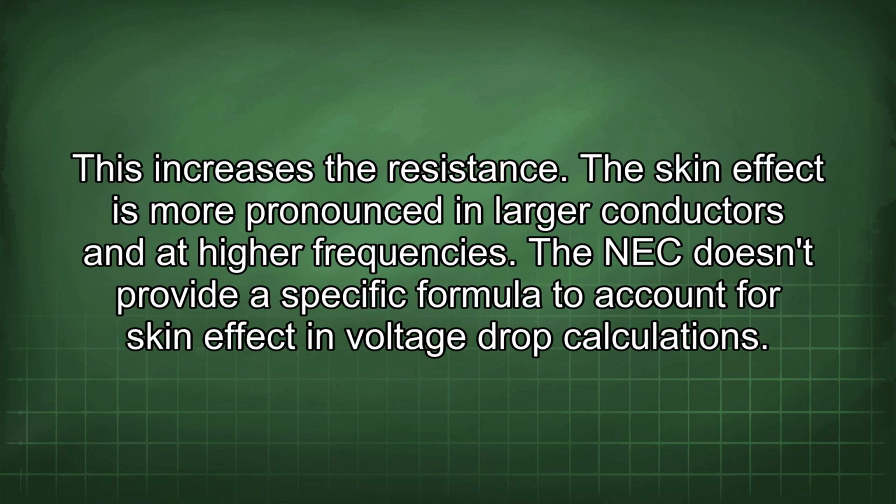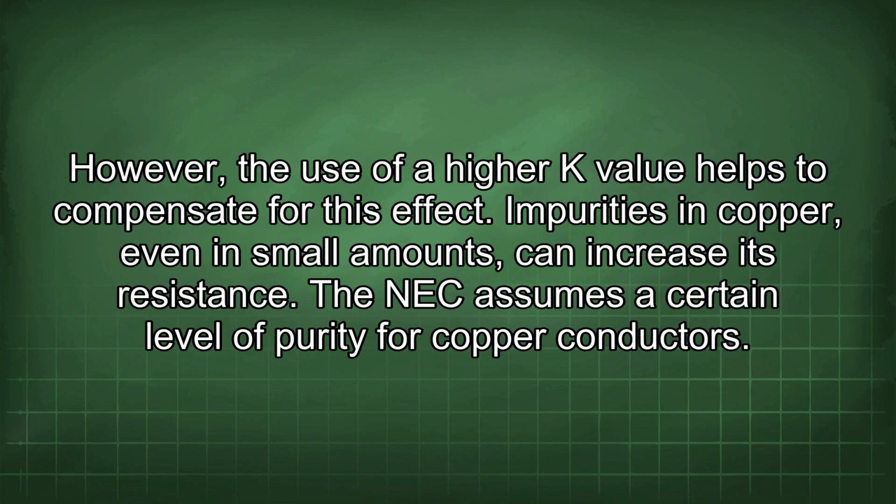This increases the resistance. The skin effect is more pronounced in larger conductors and at higher frequencies. The NEC doesn't provide a specific formula to account for skin effect in voltage drop calculations. However, the use of a higher K value helps to compensate for this effect.